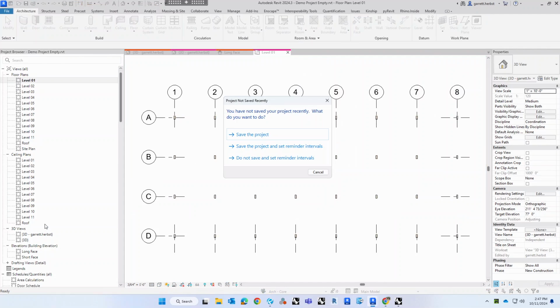In traditional buildings, high rise is a bit different, but typically you need at least 2 braces in each direction, or 2 to 4. Right now your structure is really flimsy in the lateral movements, so that diagonal bracing stiffens it up.